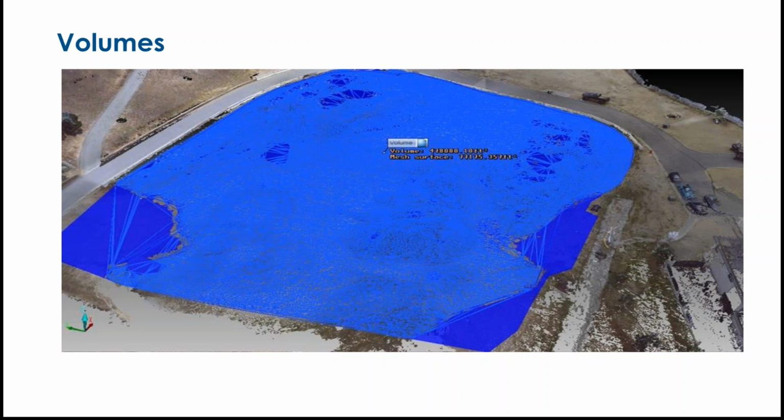This is a very quick way if someone's wanting to verify pond volume before they pack up and take their tractors. Within a few scans, you can cover a very large area, register that in also just a few minutes, and then build this mesh to get your volumes.